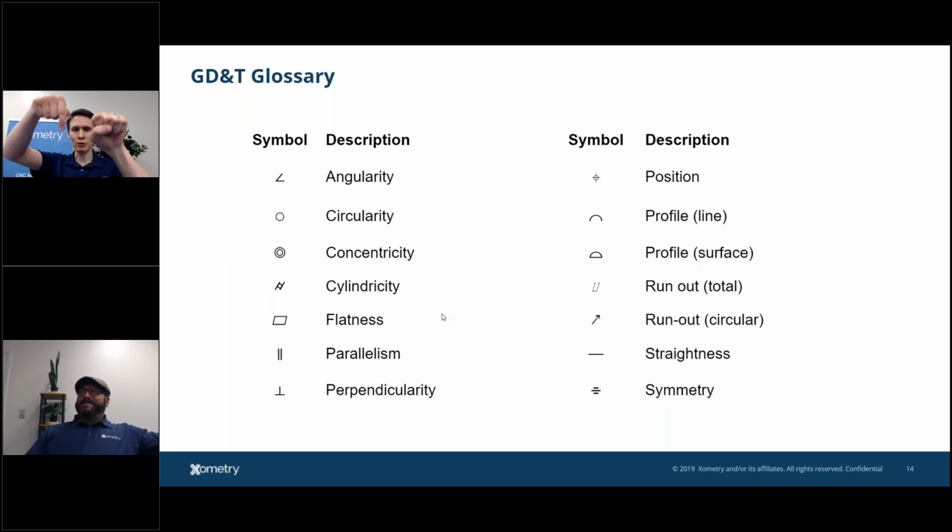A lot of times I'm using a probe and I'm touching off. I'm finding that using a probe, you need some physical space. And I'm getting a little ahead of myself, but say you do have an internal curvature that has a center that's out in space. Sometimes it's actually better to use a tolerance, like a profile, like a line tolerance, to cover that within GD&T than to use that as a central datum for that feature.